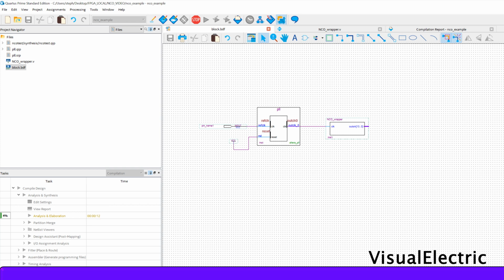In a minute, I'm going to create another module here with the appropriate interface code for my 14-bit digital to analog converter. And then I'm going to route those pins to the 14 pins of the DAC. Before I do that, I'm going to test this design using Signal Tap. If we configure Signal Tap properly, we should be able to see the sinusoidal waveform on these pins. So analysis and elaboration is successful.